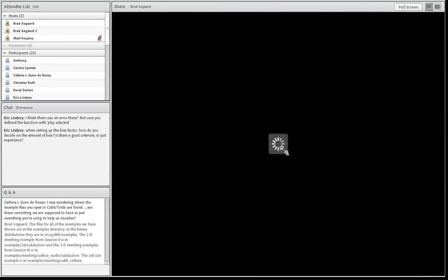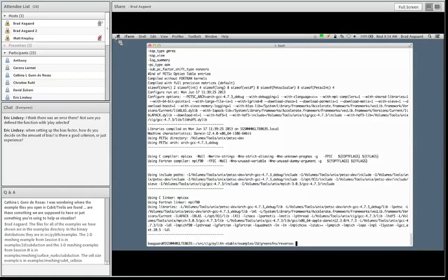So here's a little bit of a departure from what we've done in the past. We want to change the problem type and have it read in the Green's function. On the command line, we set the problem type: --problem=pylith.problems.GreensFns. This tells PyLith to change the problem type to Green's functions.